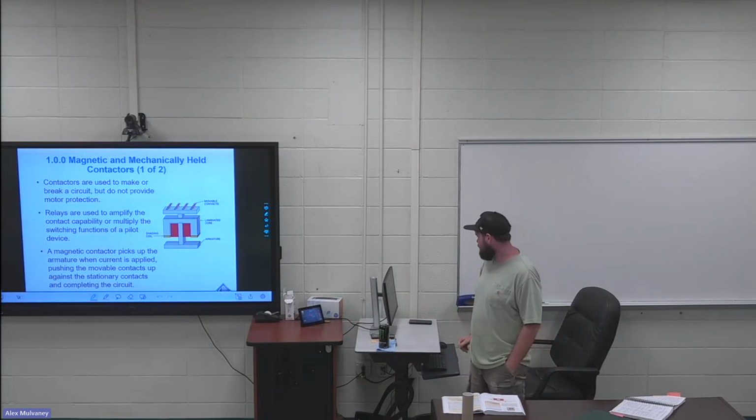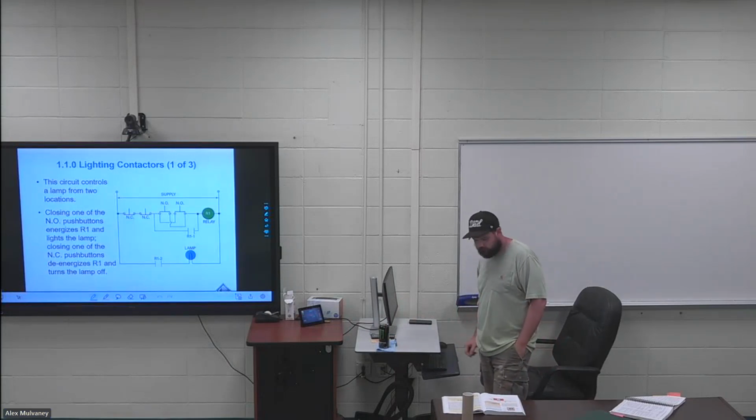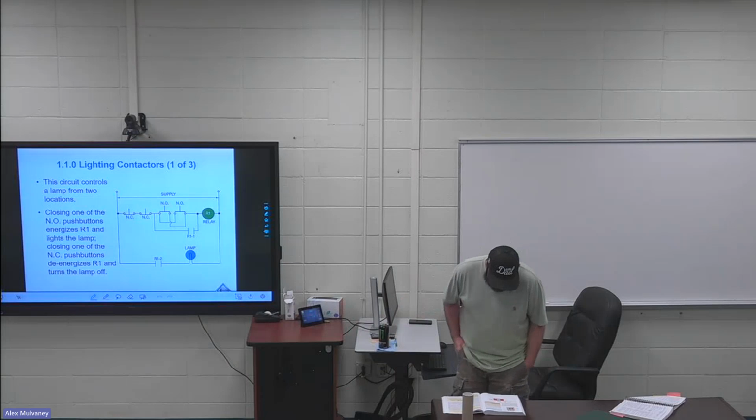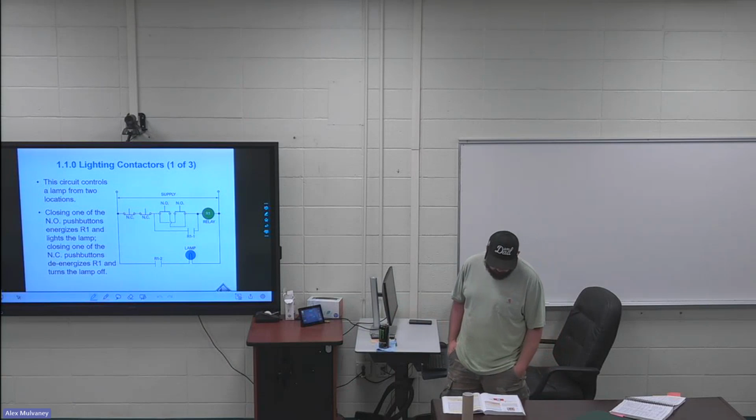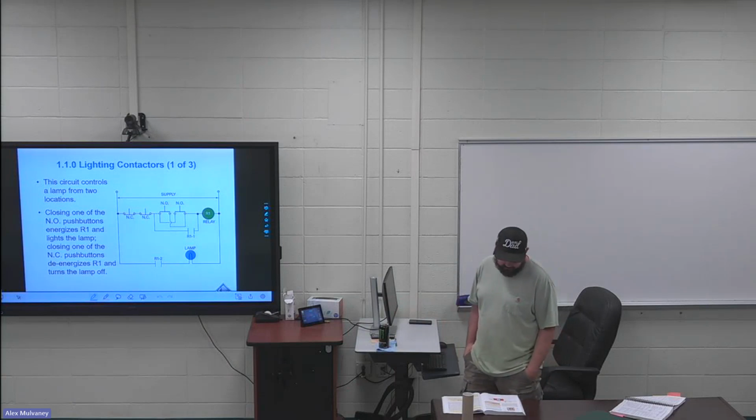Lighting contactors, 110. First sentence of lighting contactors is highlighted. Filament type lamps, examples tungsten, infrared, and quartz, have inrush currents of approximately 15 to 17 times their normal operating currents.